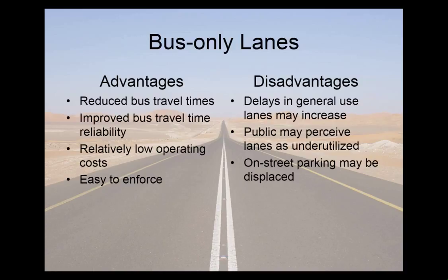The advantages of bus-only lanes are that they reduce bus travel times, they improve bus travel time reliability, so how often buses arrive on time. They're relatively inexpensive to operate and easy to enforce.